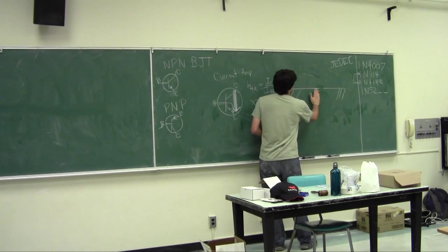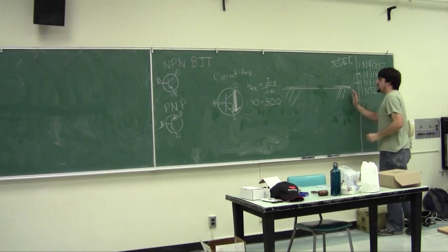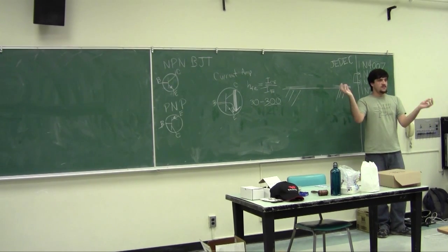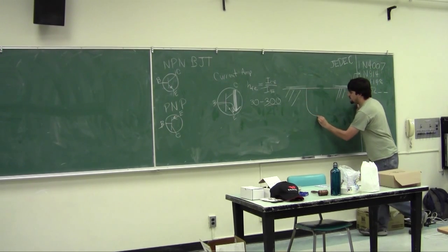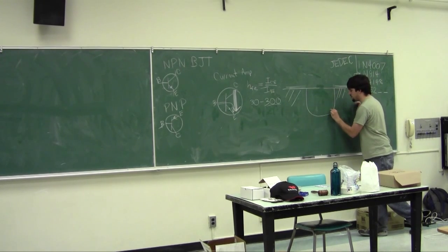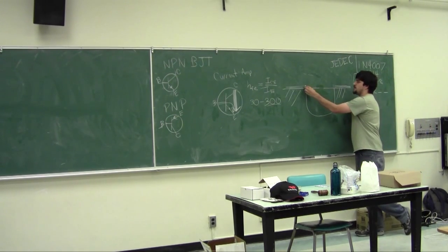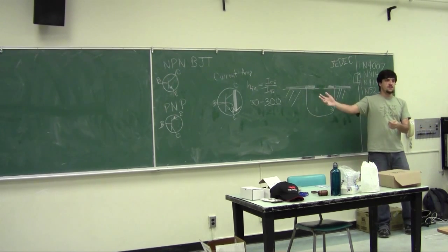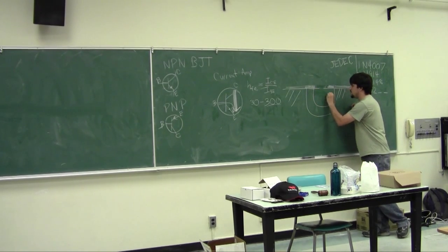So what you do as a manufacturer is you mask off the wafer, except for this one section. You then put it in an oven in an atmosphere that is tainted by some negative element, and you grow a fairly large region of N semiconductor. You now wash the resist off, reapply a new resist, and instead of it going all the way out there, you have the resist go a little bit farther in. You now take the same wafer, you put it in a different oven that is slightly tainted by a positive element, and you grow a positive semiconductor.